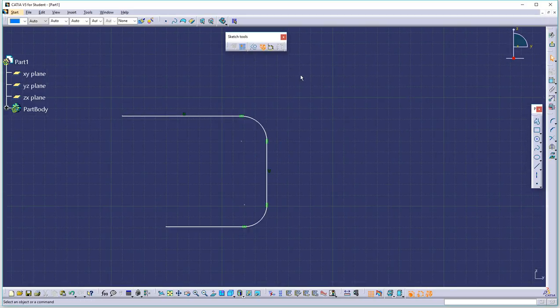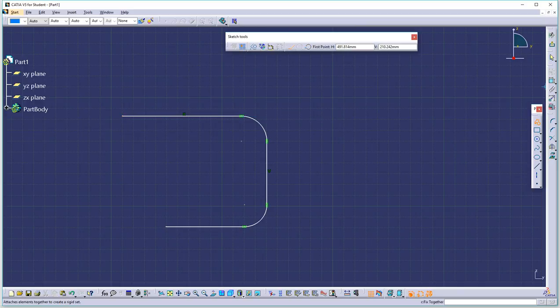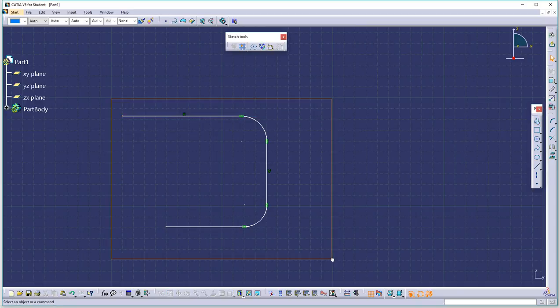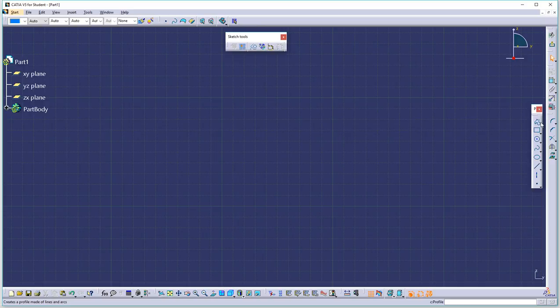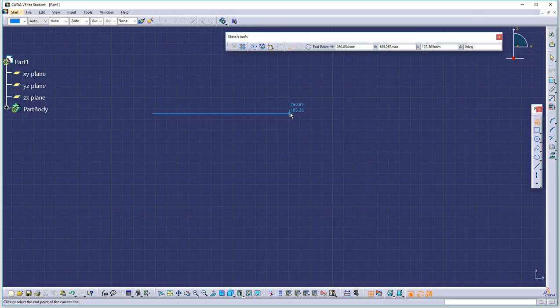If I do the same thing without the geometric constraints on, let's delete this one. Okay. Tap, press and drag, or the sloppy tap as we call it, and then tap. And then notice it's picking up the tangency there. But now it's not going to create it because my icon at the top is not on.